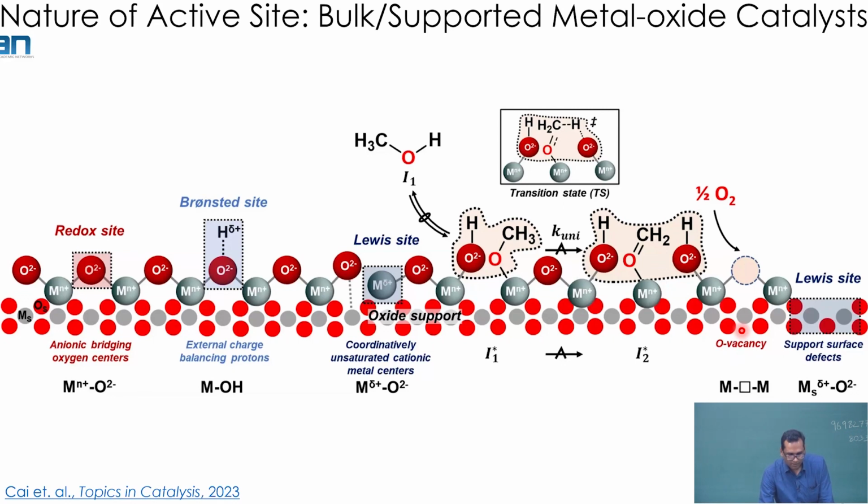We can have leaching, that is, because of the harsh reaction environment, some of these active materials are flying off the support surface, and that can cause some catalyst deactivation. We can have sintering, that means some of these smaller size particles are coming together to make a bigger particle. And we can have a support transformation or the support hydrolysis or collapse, where because of the reaction environment, the support structure is either changing or collapsing in terms of the surface area and all, which is detrimentally affecting the catalytic processes. On top of that, because of the reaction conditions, there can be different types of catalyst deactivation.